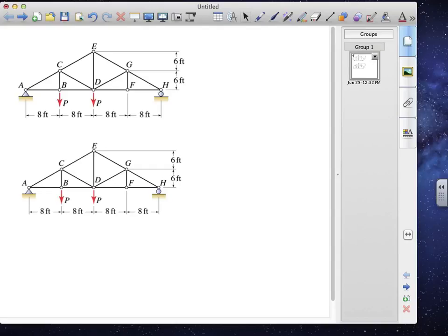In example 2, we're given that the load P is equal to 4,000 pounds. Here we have a truss with 13 members and 8 joints, and the force supported by member DE is specifically requested. Let's make some observations about the problem before choosing a strategy.